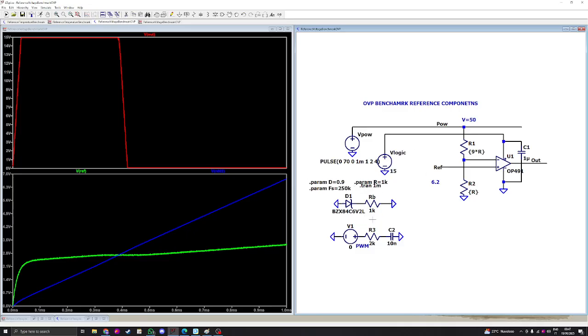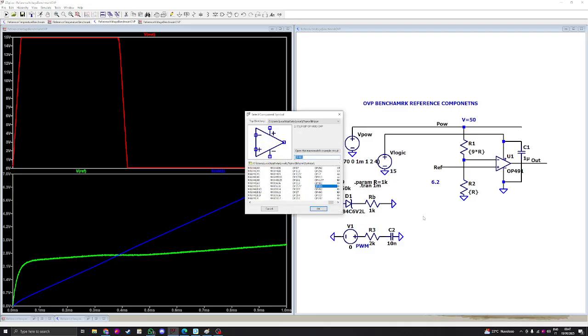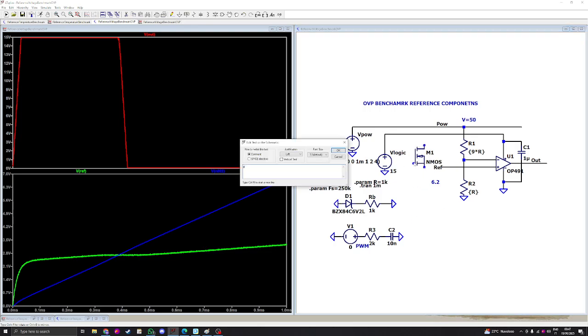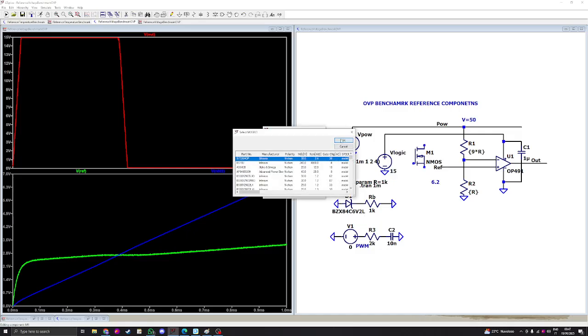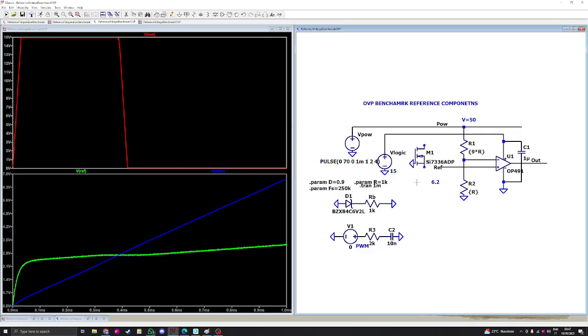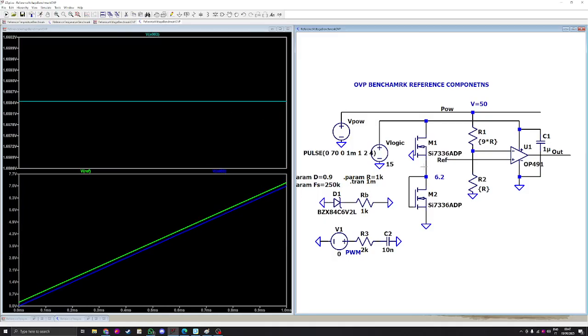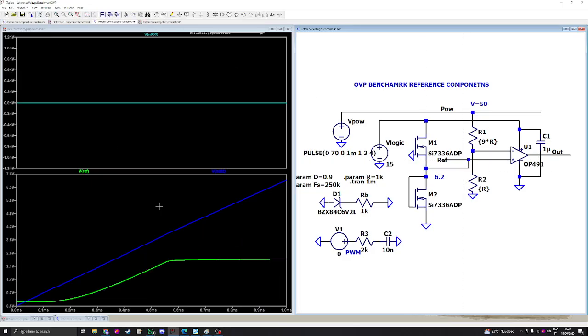So now let's use the third one, and actually it involves the two MOSFETs like this. Let's pick the first of the list. The first had the ground at the gate, and the second had the short between the gate and the drain. Now this one should give around 1.6. Let's verify it before running the simulation, and it does 1.65. Good. So now let's take the reference and connect it to that.